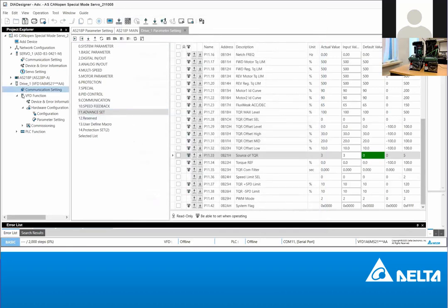Now, if you come to the VFD function, this is DR Designer. Then you come to parameter settings. So this is my drive. There's an internal PLC. I don't need that for this training. I'm going to the VFD function of the drive. I expand it. I come to hardware configuration. If I expand it, there's configuration. I come to parameter settings. In parameter settings, you can see this is drive 1. It has already opened the parameter setting page for us.